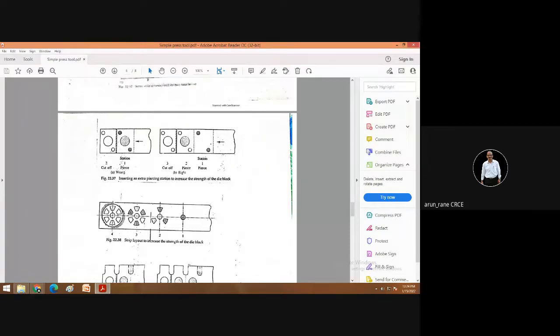6 holes, and this is one more, so 7 holes need 7 piercing punches plus one blanking punch for the blank, and the piercing punches will be close to the blanking punch. So the punches will be very close. The gap between two punches will be very thin, and during working this wall may collapse and an accident will happen. And corresponding to 7 punches there will be dies also in the fixed half. To fix those dies you will need inserts, and inside the inserts the die cavity will come. So it will not be possible.